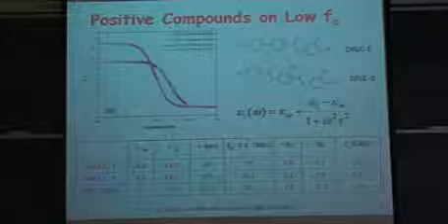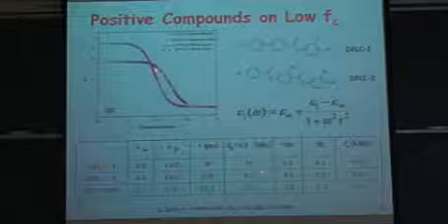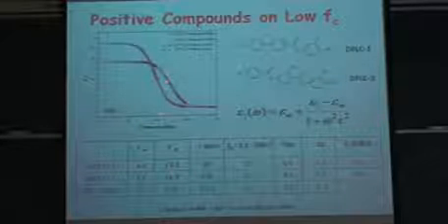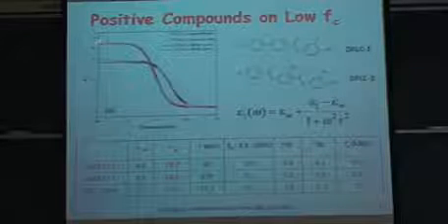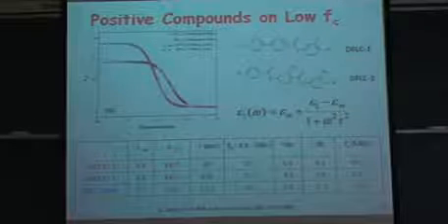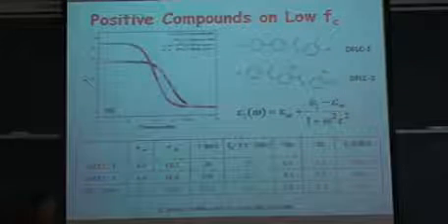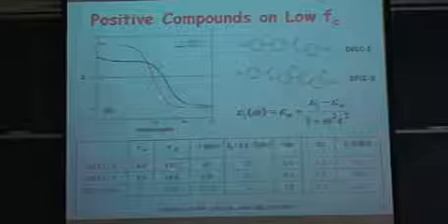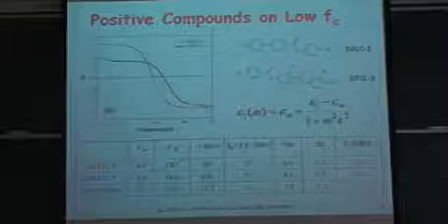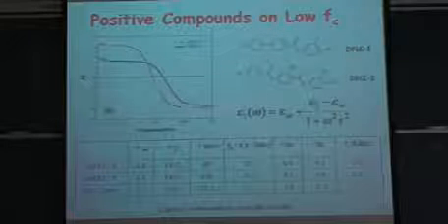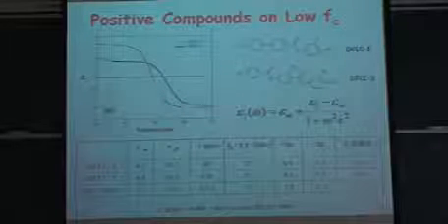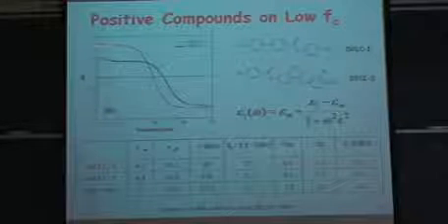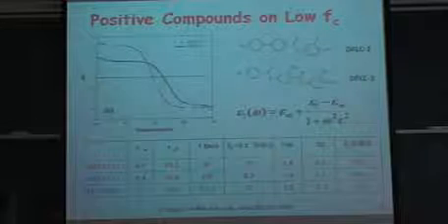We can see this one has a three times lower dielectric relaxation frequency than the first one, and also a larger dielectric constant value. And this figure shows the dielectric anisotropy. The negative one is constant, it doesn't have dielectric relaxation. So we can see the crossover frequency is also 3 times better, and the dielectric constant is bigger.